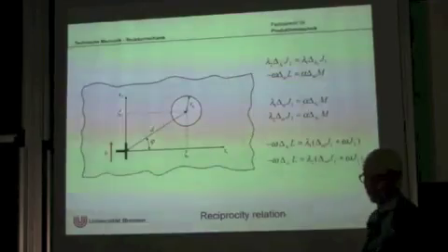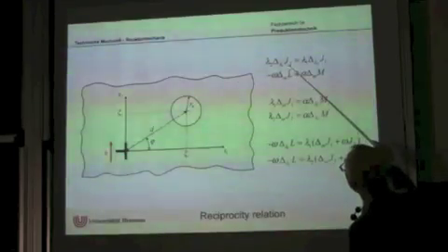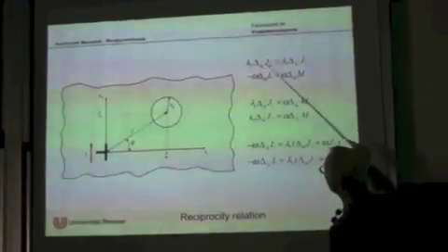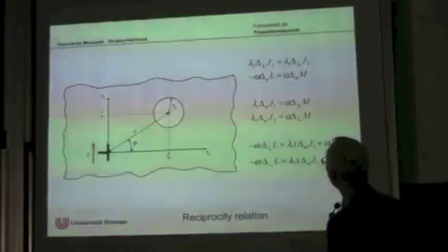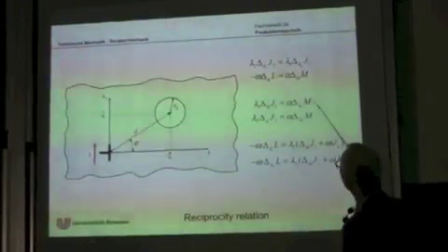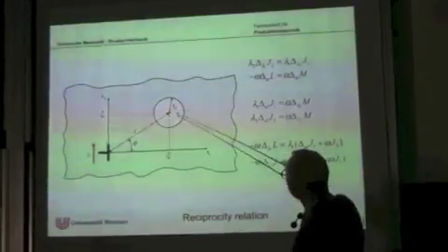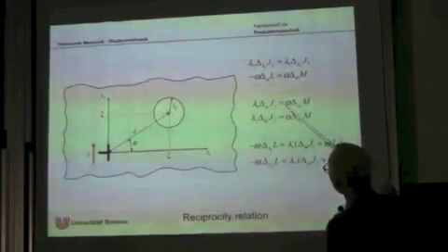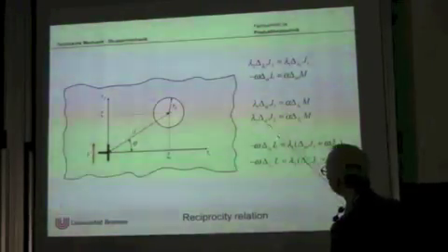And again, since if you have small material translations, the change in J2 due to a change of lambda 1 is proportional to lambda 1, and therefore you can immediately introduce influence coefficients. Another one that we will need in the following is, if we look at the self-similar expansion of the hole that is given by this parameter alpha, then we can give the following reciprocity relation that I will use in the following.